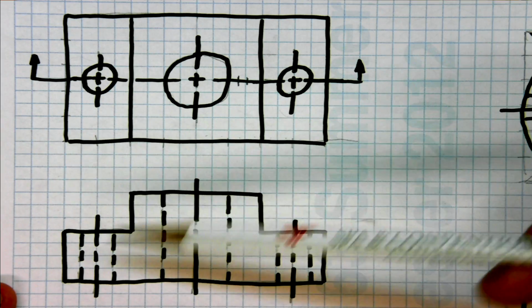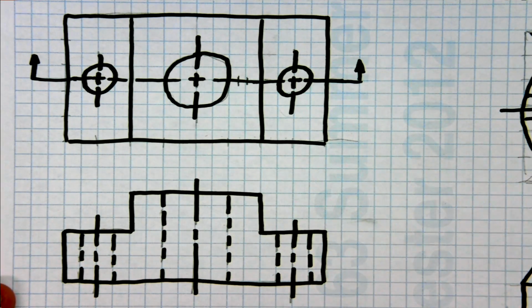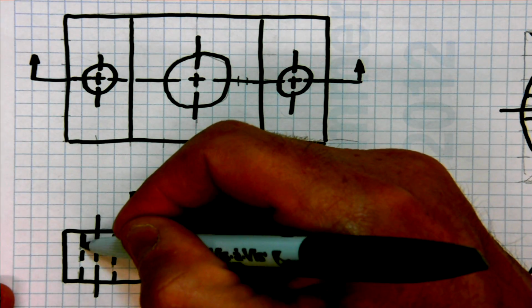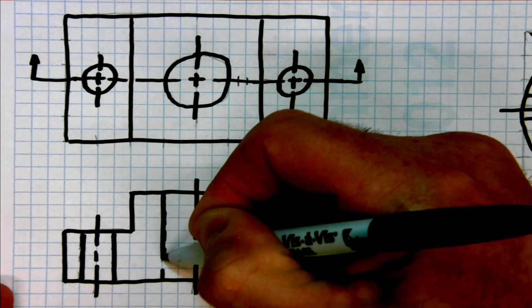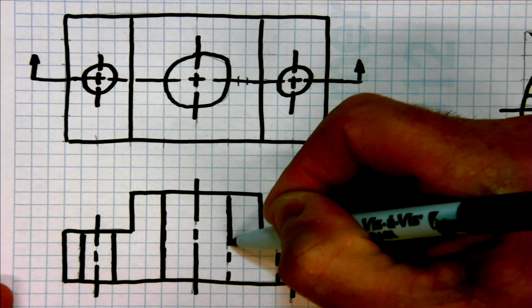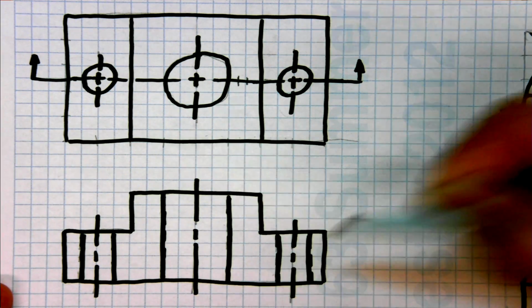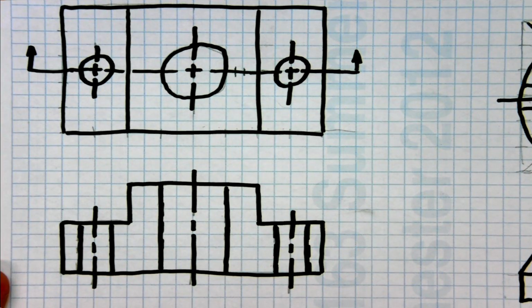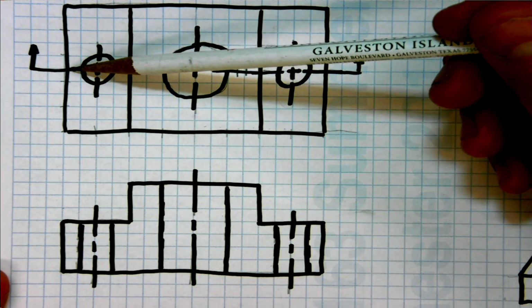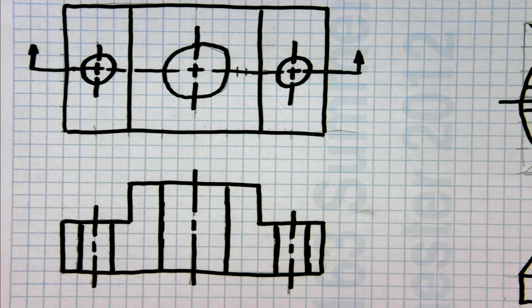Well, now these lines here become object lines. You can see these. Again, remember, in the context of this class, there will be no hidden features. So these become exposed, thus they go from being a hidden type feature, in this case a limiting element of cylinders, to object features you can actually see. Wherever the part is cut by the cutting plane, right in here, right across to there, right across to here, and here, will show with cross-hatching lines.